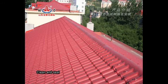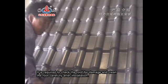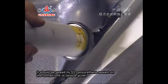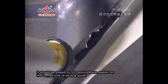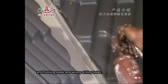Clean and seal. It is required to check the roof for damage and clean the roof carefully after installation. It should be sealed by 531 polyurethane sealant on the connections of the oblique gutter and flushing panel and wrongly drilled holes.